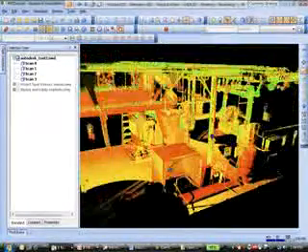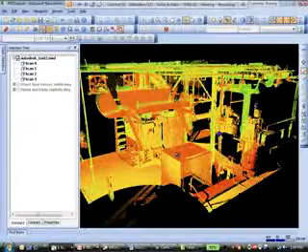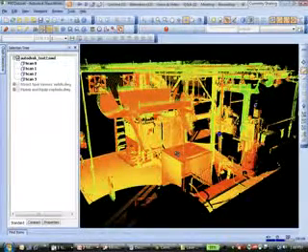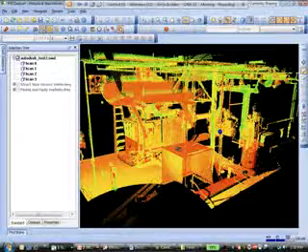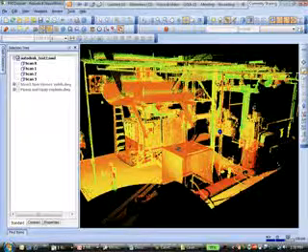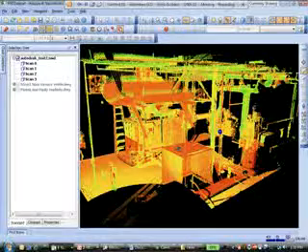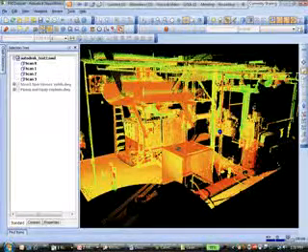But a lot of times, what happens is you're assuming that pipes are level, that they're straight. Over time, elements will tend to sag. You might find dents, and especially with deflection on some of these different items. The laser scan is going to give you a true picture of what's happened in there, and this becomes very useful going forward. If this was drawn as a CAD file, you may show a pipe being completely horizontal, but in reality, because they didn't place the pipe hangers properly, it's deflecting an inch or so in the middle.